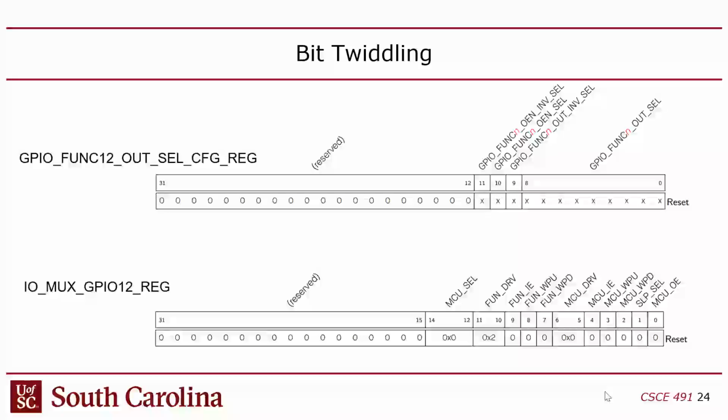So basically, in this case, the function is 9 bits. So I can select any of the internal signals and route them out by selecting this 9-bit field. And there's a big table in the reference manual, which is linked on Blackboard, by the way. There's a link to the reference manual. There's a table with what all these codes are.